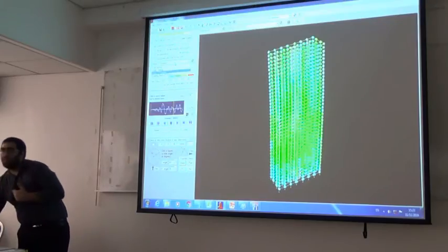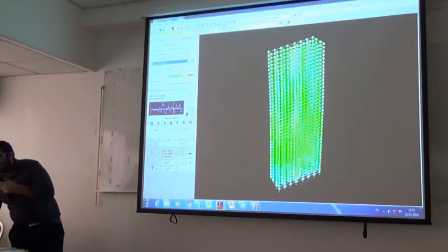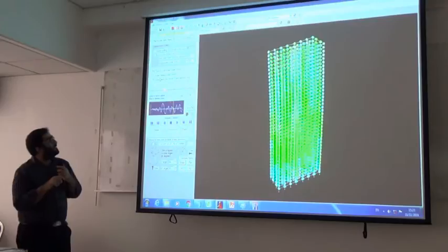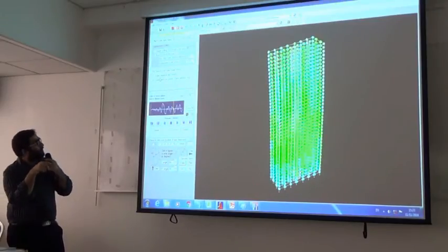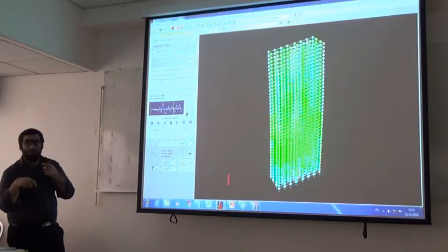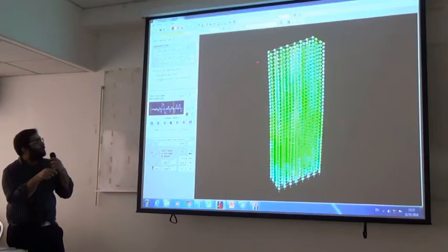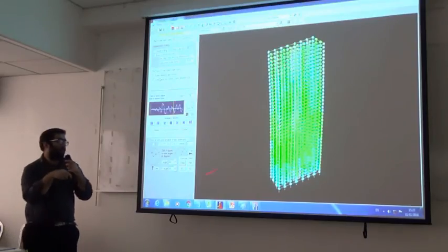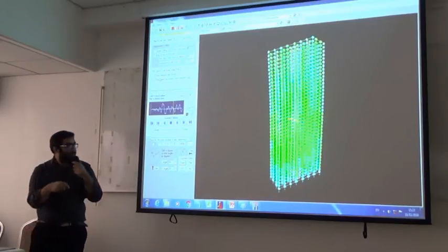Shabir, ours doesn't have a dot. That one, you have to select this option over here. I just selected this option just to show you that you will have a dot. Otherwise, you will just have a red color or blue color. You just need to select the option "Components are colored, frame elements only." So the component will be colored, the element will not be colored.